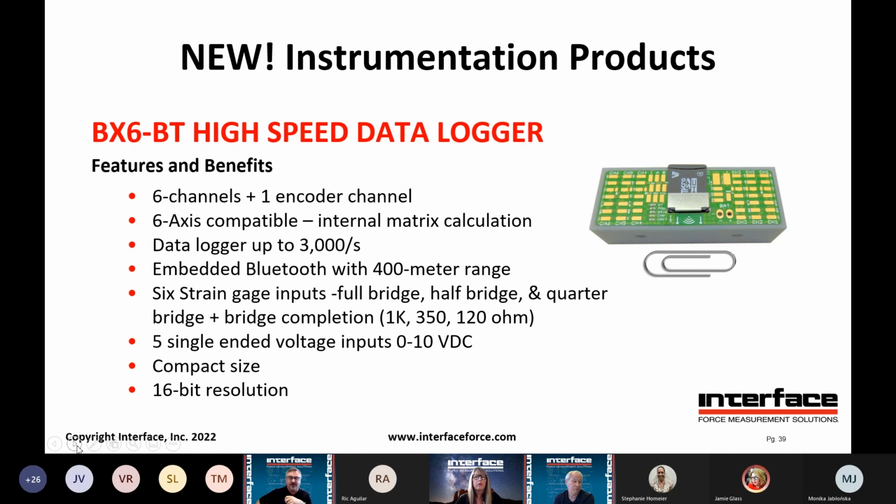The channels can be either strain gauge, and that could be full Wheatstone bridge like a load cell, or it can be actual strain gauges applied, and that can either be half or full bridges or quarter bridges, and has internal completion resistors. It's got voltage inputs too, so any of those channels can be set, say, for a voltage input, if you had a sensor with voltage output. 16-bit resolution. It can log to the SD card and broadcast data over Bluetooth simultaneously. So if your wireless connection falls over for some reason, you can still grab the data off the SD card later.